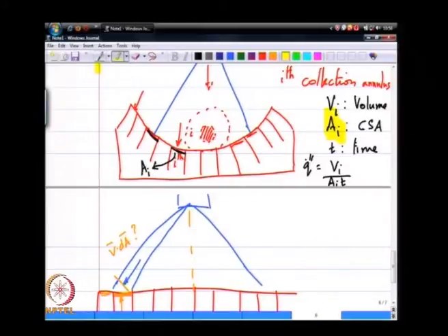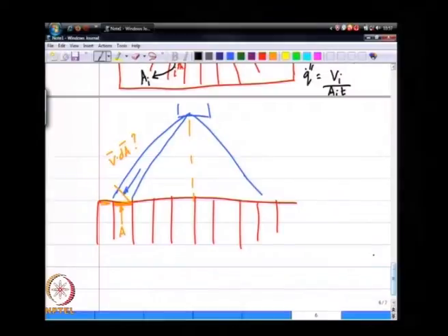If I have 20 annuli across the circle, and if I want to calculate Ai for the ith annulus, I use the geometry of that annulus: the inner radius of the annulus and the outer radius of the annulus. I am essentially assuming that the flow is entering the annulus nearly perpendicularly, which will be the case if I have them in a circular arrangement. If I have them in an inline arrangement, it does not necessarily be the case.